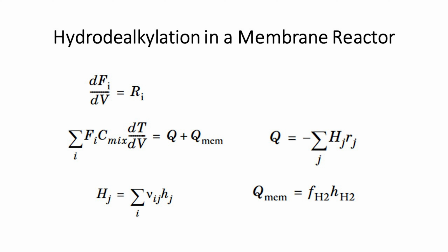So the reaction engineering interface automatically sets up and solves equation 3 and equation 4 when you select the predefined plug flow reactor. To adjust the default model to account for hydrogen entering the reactor through a membrane, the flow term F H2 has to be specified and included in the material balance for hydrogen.